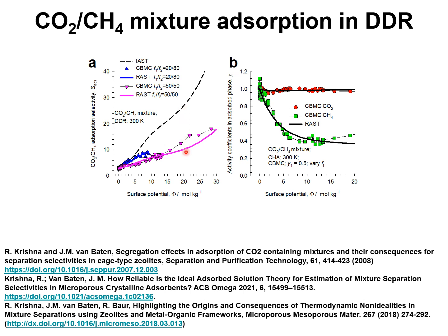This lowering in the adsorption selectivity is because of reduction in competition between CO2 and methane. Methane suffers less competition from the most strongly adsorbed CO2, and therefore the adsorption selectivity is lower than is anticipated by the ideal adsorbed solution theory.